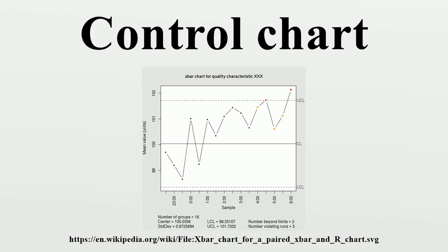Performance of control charts. When a point falls outside of the limits established for a given control chart, those responsible for the underlying process are expected to determine whether a special cause has occurred. If one has, it is appropriate to determine if the results with the special cause are better than or worse than results from common causes alone. If worse, then that cause should be eliminated if possible. If better, it may be appropriate to intentionally retain the special cause within the system producing the results.